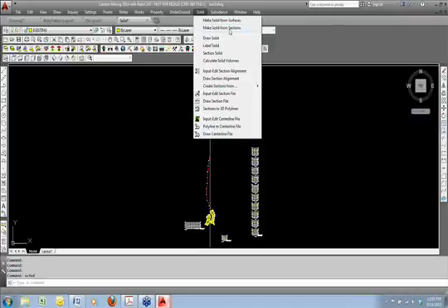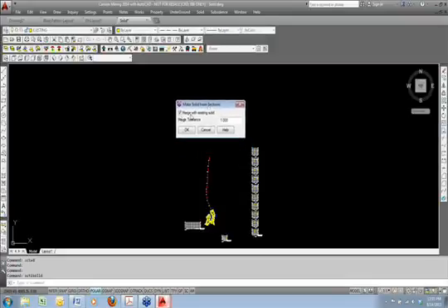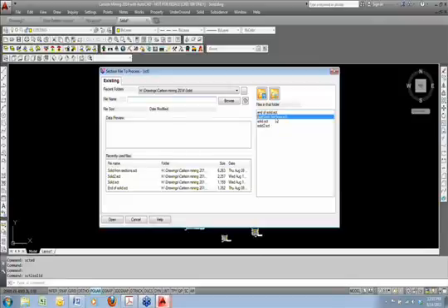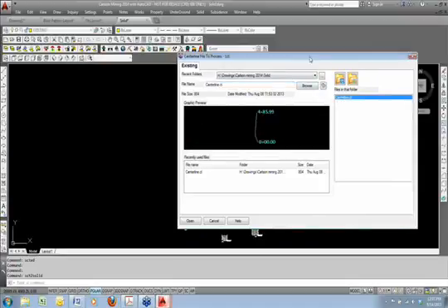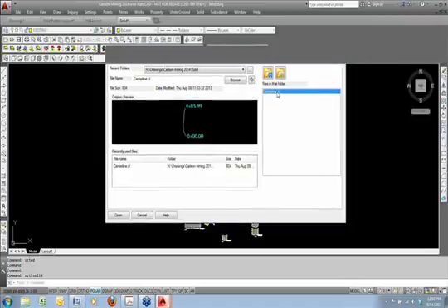So now we'll run the command, make solids from sections. Those are the two things it needs, a section file and the alignment. And there's an option also to merge with existing solid, which is what I'm doing here. I'm continuing off an existing solid, or if it was a brand new one, you would just turn that off. But I'll just leave it on, hit OK. Section file to process. That was the one I just showed you, solid from sections. Centerline file. That's just the graphic center line of this red polyline you see there. Just your typical centerline horizontal alignment.